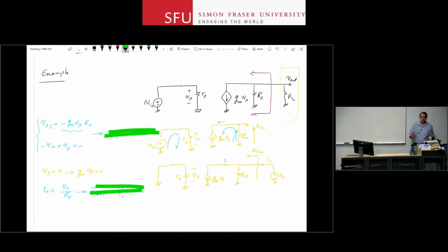Do the same thing for the Norton equivalent circuit. Find the Norton equivalent circuit for this network. And also try to calculate the equivalent impedance using the method that you know from electric circuits. So you have the open circuit voltage, find out the short circuit current, and divide the two to each other to see if you get the same value as we did here. You must. Okay?